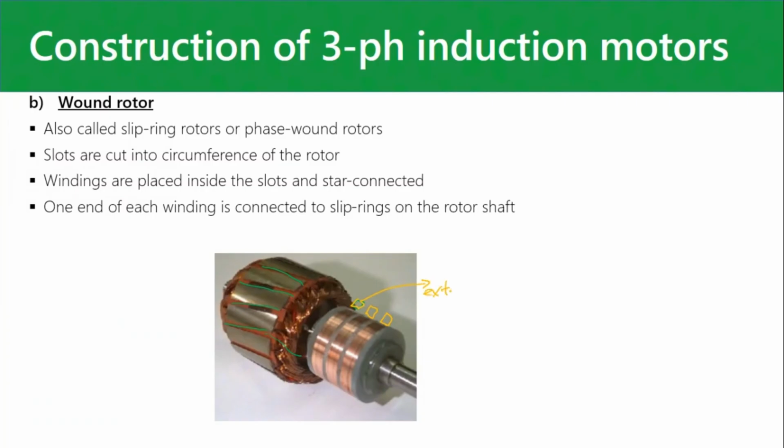So this type of rotor, you can have external startup resistors. And you use these, it not only limits the startup current, but it also gives it increased torque at the low end of the speed. So you use it for cranes and hoists and lifts and things like that. Okay. So it'll look like that.